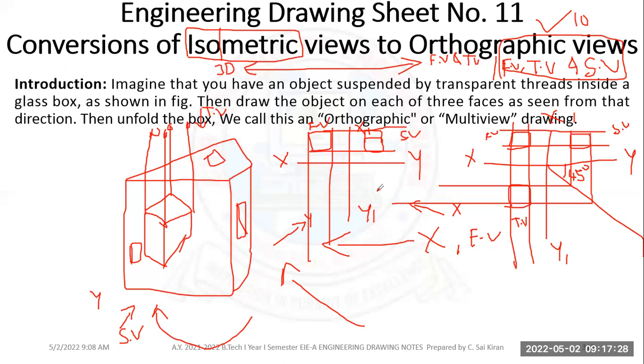Or else if you have a compass and the distances are very small, then you can use this one. Okay, what you have to do is project till the X1 Y1 XY reference line. And then this is your radius. Keep your compass pointer here, your pencil here, and draw the arc till here. So you'll get one arc. This is your r1, radius 1. And similarly you measure this, which is your radius 2.